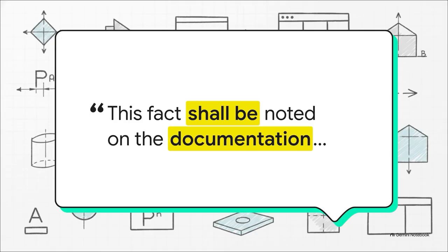That's it. If the drawing title block is missing this information, or if it ambiguously just says tolerances apply, kick it right back to the design engineer. Do not accept the liability of guessing. Forcing the client to specify ASME Y14.5 2018 or the applicable ISO GPS matrix standard is the absolute best way to guarantee that this ambiguity never costs you a scrapped production run.